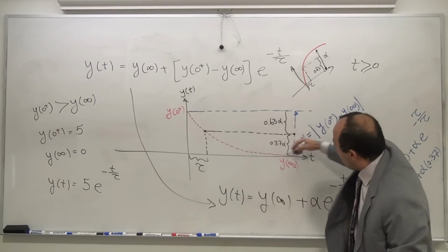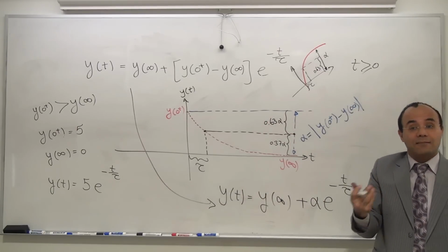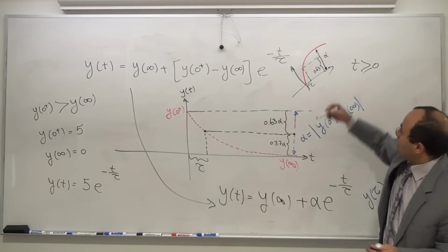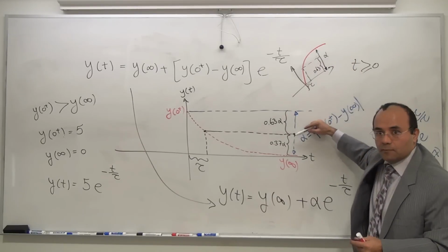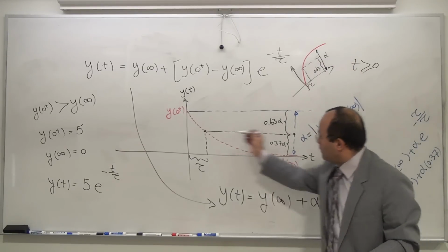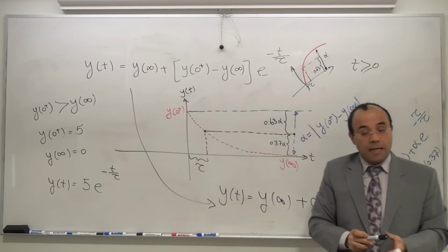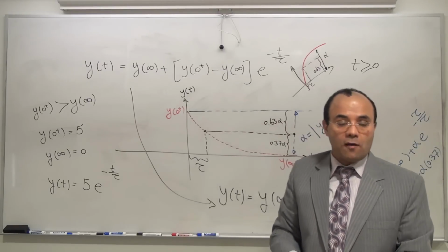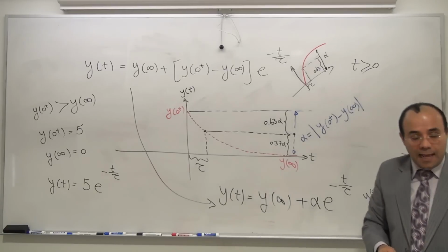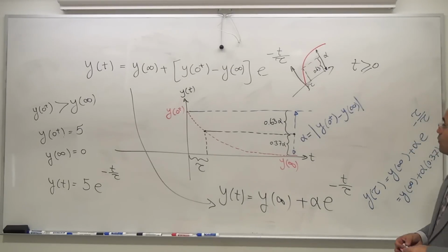If you are falling, come down 63%. I want you to remember that number, 63%. Rising, rise up. Falling, fall down. 63%. Go to the red signal, come back and get the tau. It was interesting, I saw from last week, lab number 4, the majority of the class were able to find it very nicely, very close to the actual value.